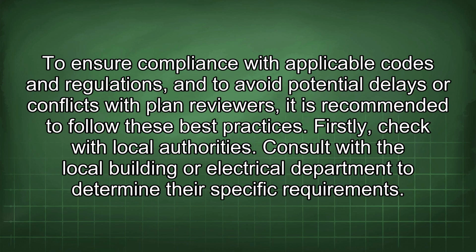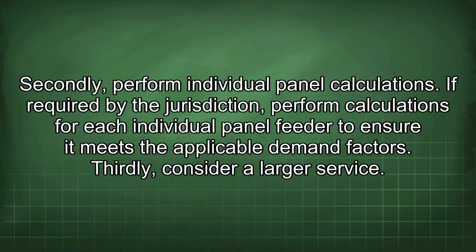To ensure compliance with applicable codes and regulations, and to avoid potential delays or conflicts with plan reviewers, it is recommended to follow these best practices. Firstly, check with local authorities. Consult with the local building or electrical department to determine their specific requirements. Secondly, perform individual panel calculations. If required by the jurisdiction, perform calculations for each individual panel feeder to ensure it meets the applicable demand factors.